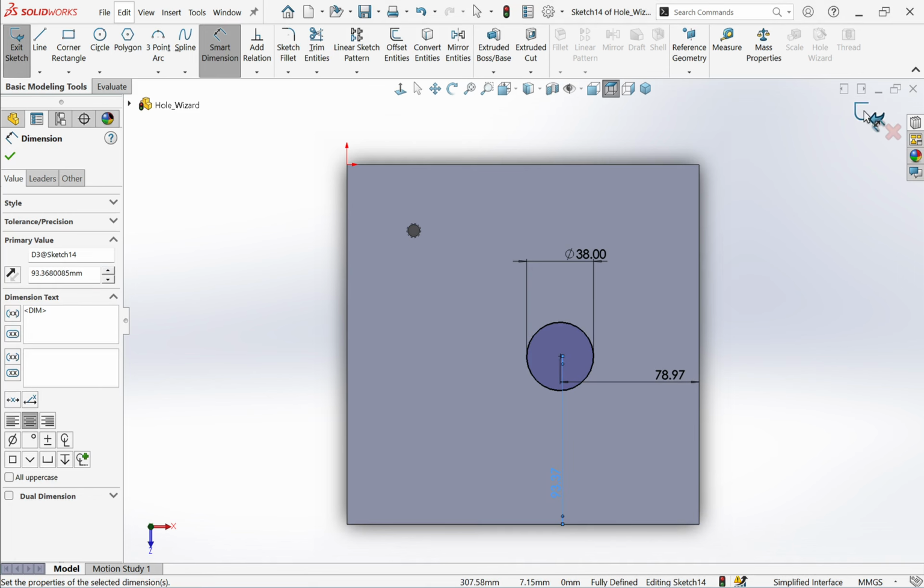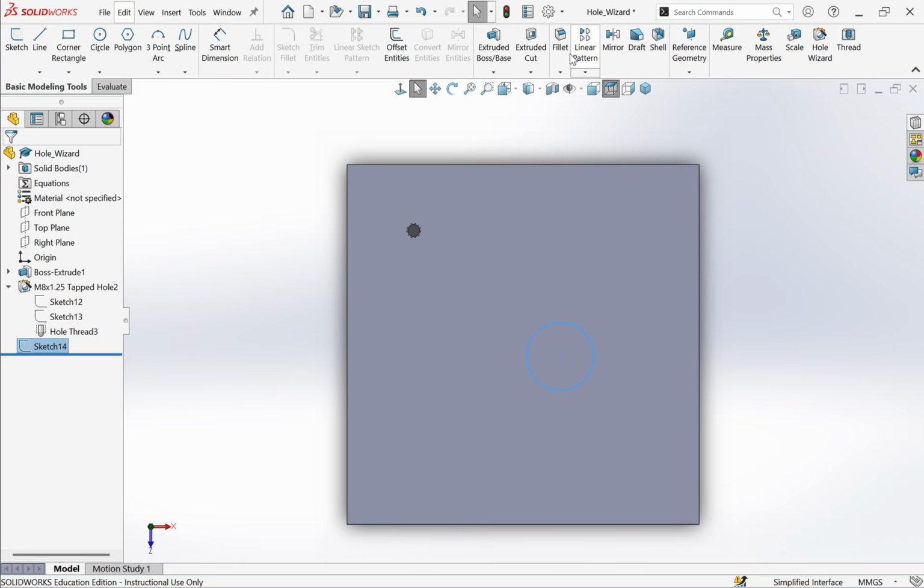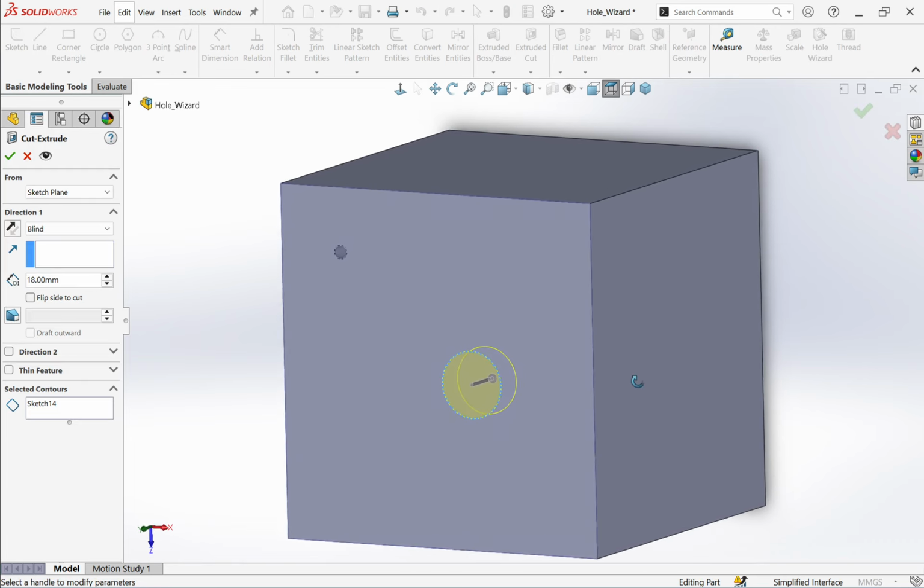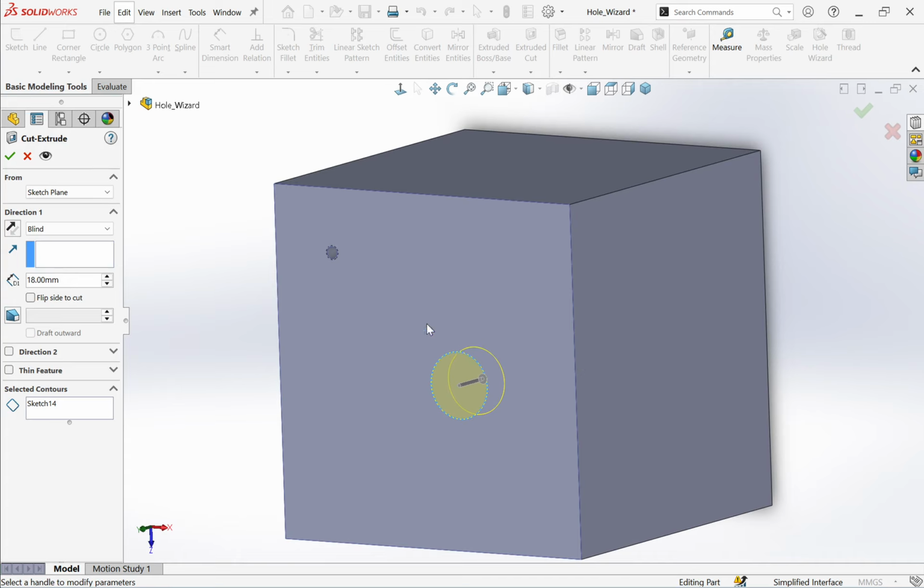It's nice. So you finish that. Now we have to create a cut extrude because we need an edge of cylinder. You need to look at your part. I'm not going to give you the answer here, but on the edge of this cylinder that we're going to have, it says M38 by 2. 2 is not the depth. You need to look at the feature and determine what the depth is. So I just put in 18.